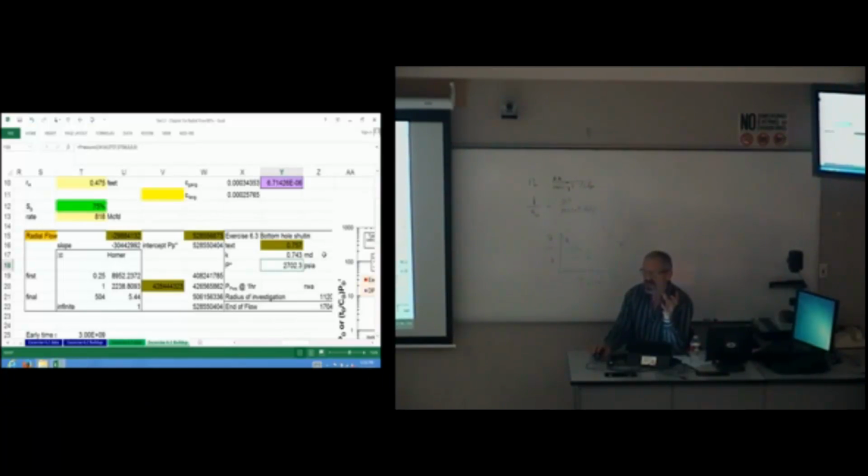The skin, in the old school we used to call them production engineers, but now they break that out and call them completion engineers. If you've got a high positive skin, that's important for the completion engineer to know. Maybe he just doesn't have enough holes in his pipe, because we're talking about a vertical well, radial flow.